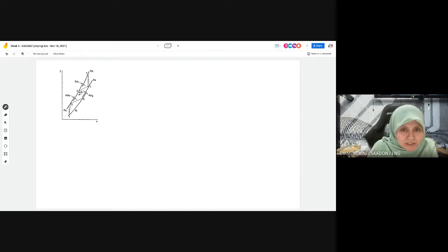So point number one, we write it as TO1. So we assume that at the inlet we have ambient temperature at number one here. So we use the total stagnation value instead. TO1 stagnation properties equals TA ambient 288 Kelvin, and then the same for pressure will also be PA.